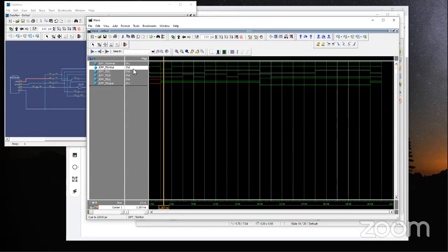That is what is meant by asynchronous reset or asynchronous preset. It really doesn't matter where the clock is. As soon as it comes, it just resets that whole thing. There can be another set of reset and preset, which is a synchronous reset and preset, which means the resetting and presetting action only happens after the active edge of the clock for that flop.